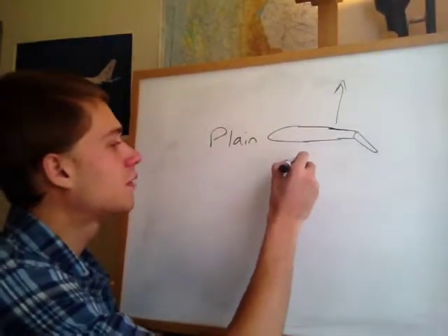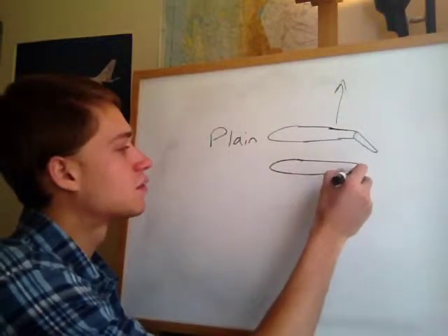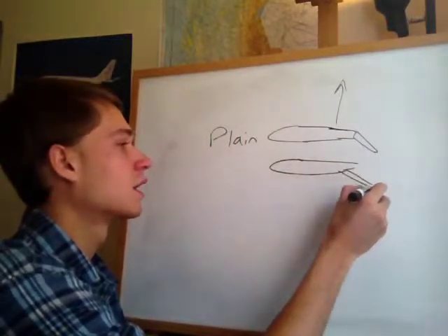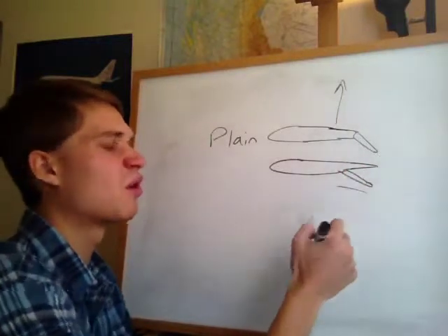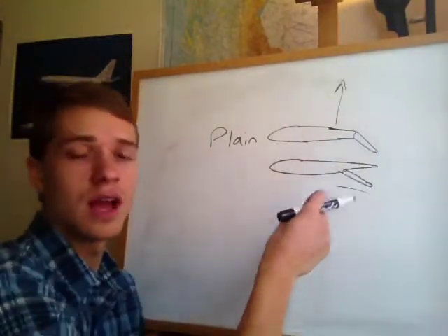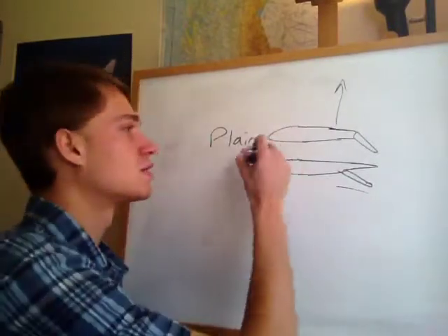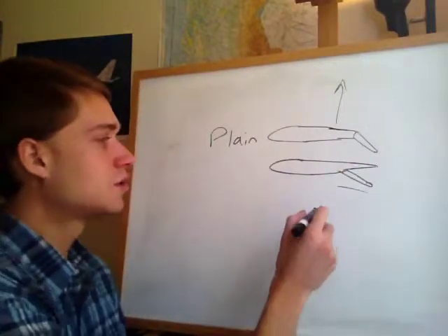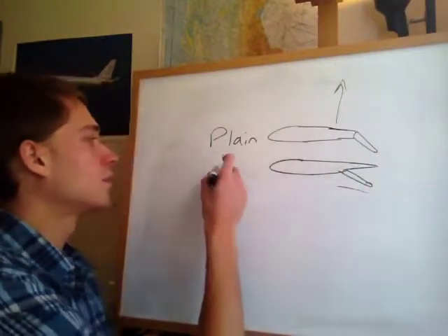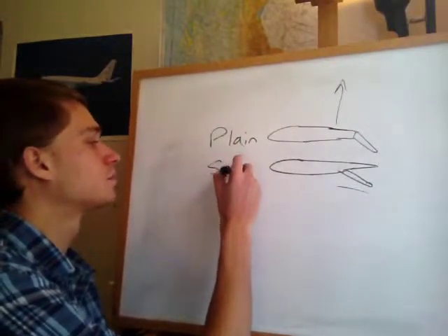And then another type of flap that you got is the split flap, and so it's just the bottom half of the back of the wing that comes down, and that tends to produce more drag. This also produces drag. All types of flaps produce drag, especially the more that you lower it, because you see it's almost like a big old scoop that you're creating right there. So this tends to produce more drag than you really like, but that's the split flap.